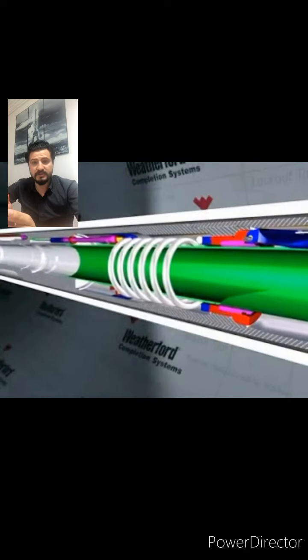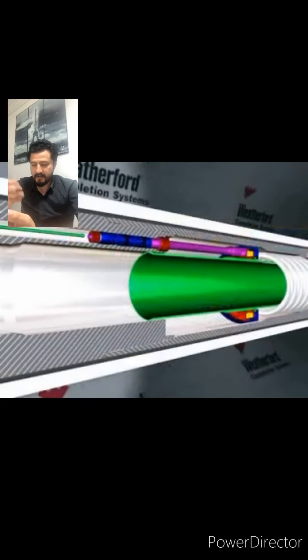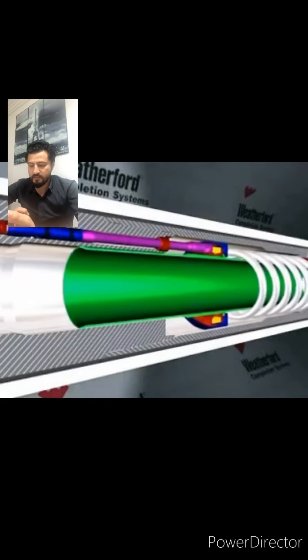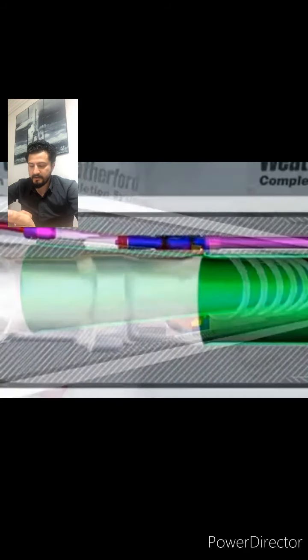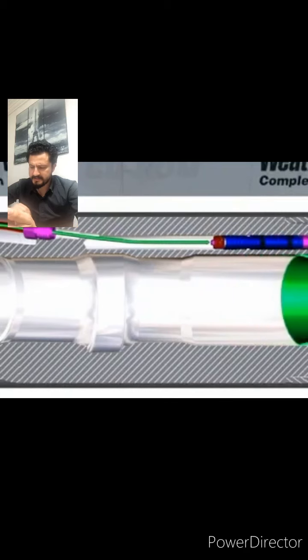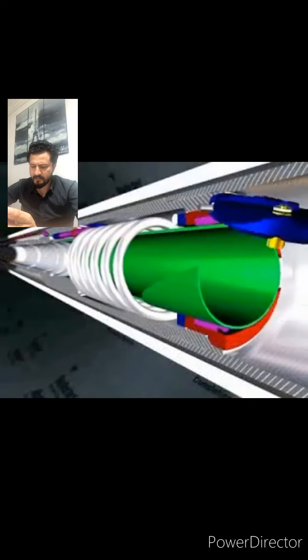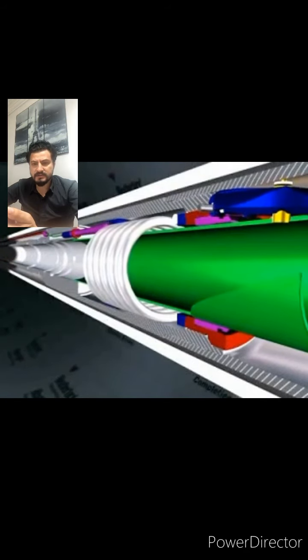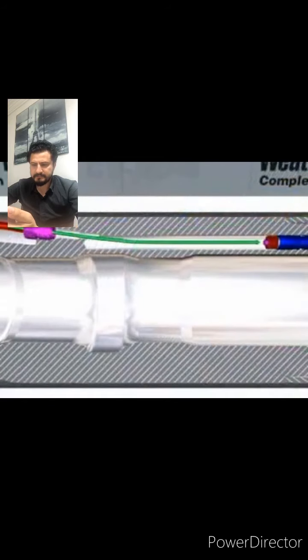When the hydraulic pressure is released, the flow tube goes back up and causes the flapper to shut in. In this way, it is fail safe and will isolate the wellbore in the event of loss of the wellhead.